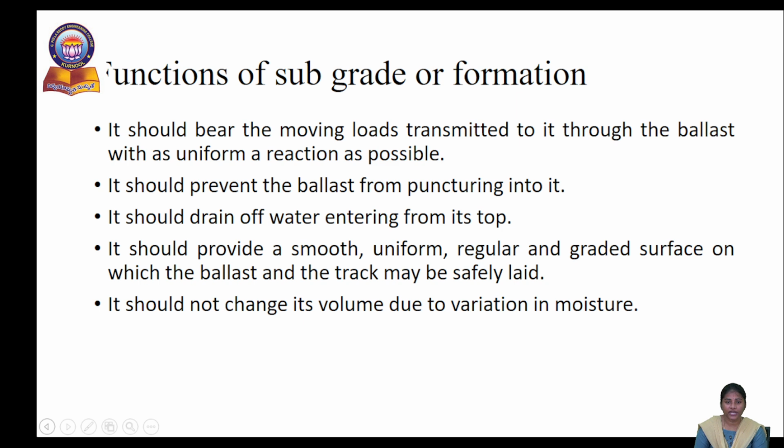It should drain off the water entering from its top. It should provide a smooth, uniform, regular and graded surface on which the ballast and the track may be safely laid. It should not change its volume due to variation in moisture. So whenever there are changes in the moisture condition, volumetric changes should not happen in the subgrade or formation.